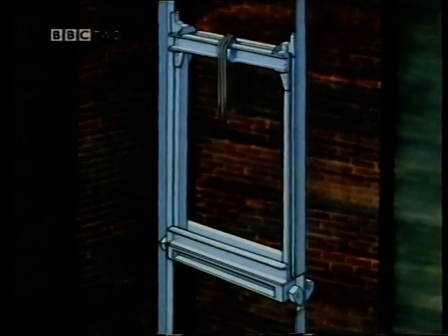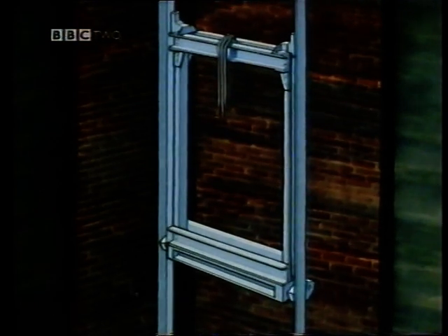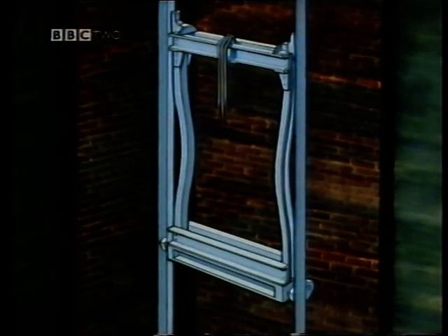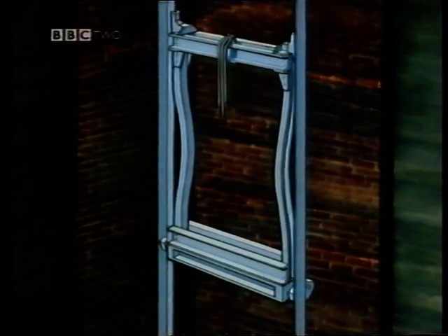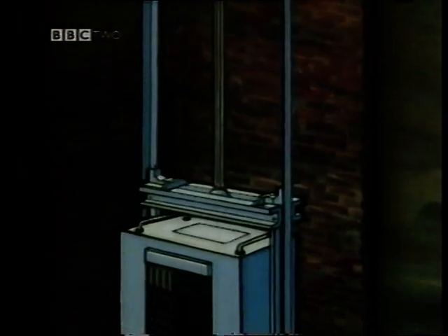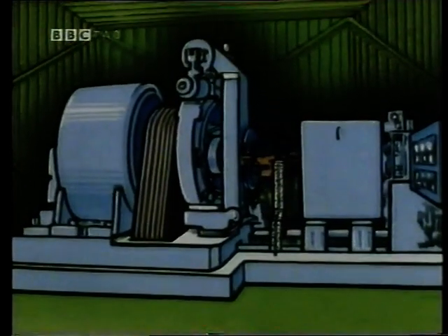So now the side members would experience compression, and then should be considered as struts under shock loading. Whereas previously they were considered as tensile members, they now need to be modelled as struts. And in general, the whole system, car frame, ropes, and winding machinery, have to be designed for these different sorts of loading.